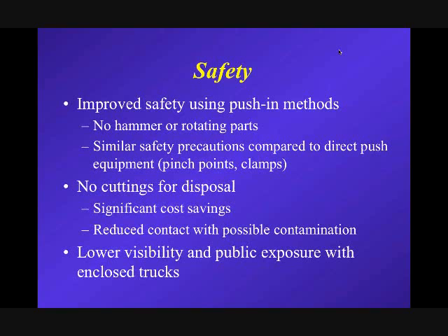And so with the CPT, you're just pushing this small diameter probe in. There are no cuttings coming to the surface. So obviously reduced cost and, of course, reduced contact of personnel with possible contaminated ground. And, of course, lower visibility and public exposure. If you have one of these enclosed trucks, typically the public is unaware of what you're actually doing.